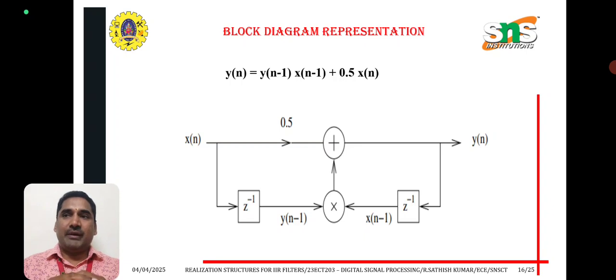This is the block diagram representation. y of n is equal to y of n minus 1 into x of n minus 1 plus 0.5 into x of n.